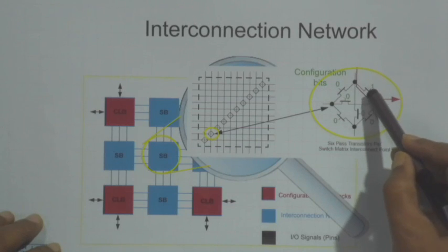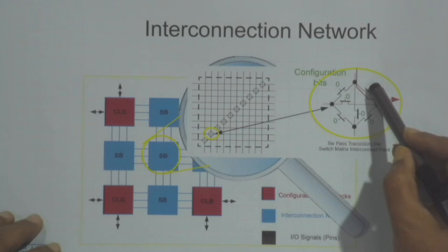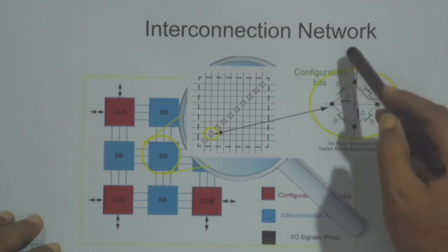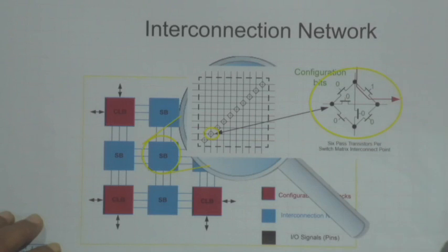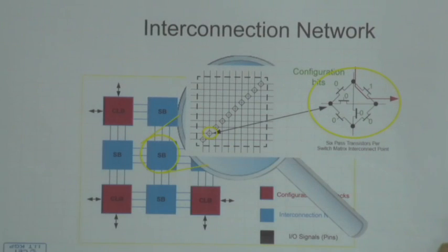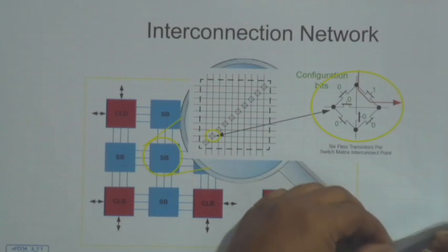This is a transistor and this is a signal that we are giving at the gate of the transistor. So, depending on the programming of the gate bit, I can program the interconnect also. Because of this programmability, FPGA actually is called a programmable gate array. Okay.